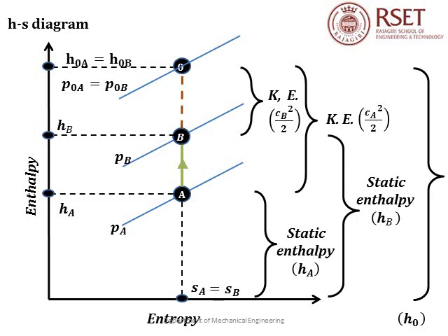The point to be noted here is that this compression was obtained not by supplying any external work. It was because of the virtue of area change. All that happened was, as the flow progressed, one form of energy got converted to another form. Here, the kinetic energy got converted to the internal energy and pressure energy of the fluid, the sum of which is represented as enthalpy.